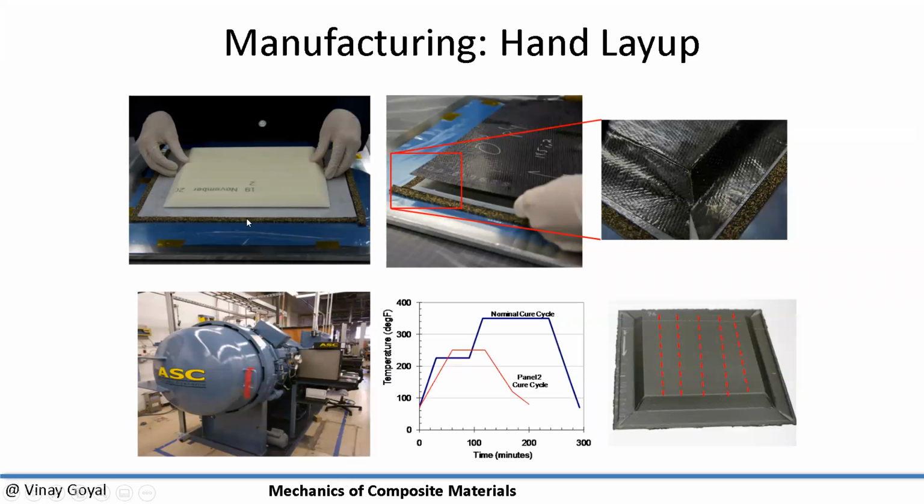And you can see these dams made of cork, which are meant to do exactly what we talked about, which is to prevent resin from flowing out uncontrollably. Once you put the core down, you put the top face sheet down, and then you're going to have these areas where we have to apply a roller. You want to pressure it so it's glued down nicely, and you do that with a roller, like if you're painting a wall.